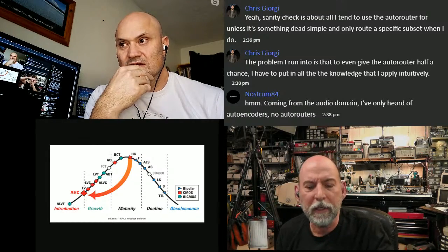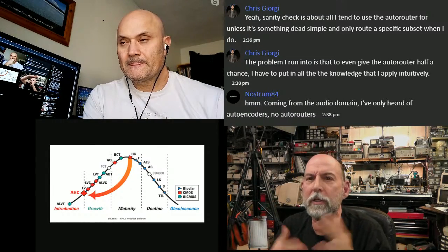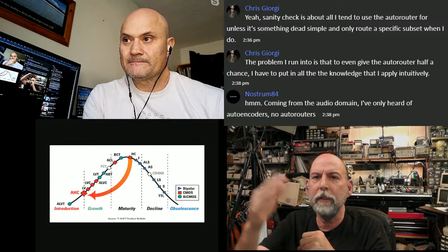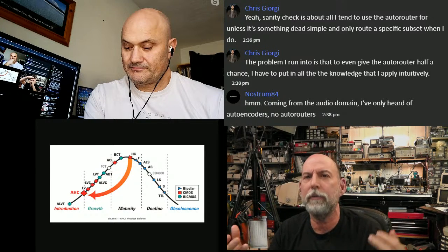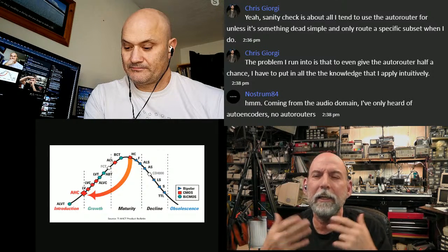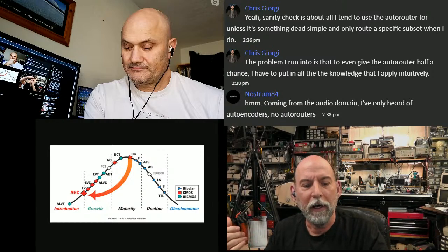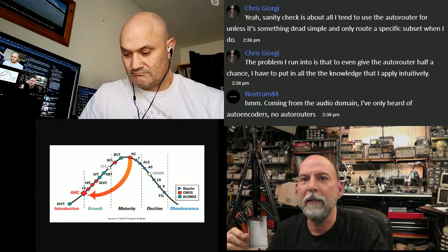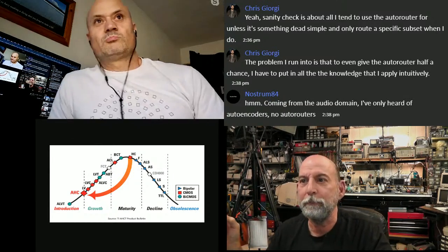That's fine, it's within limits, but if you're doing the statistics of production, the further away you can keep your traces from things like through holes, statistically, the less chance you have of a failure. So I wish it had a sort of hug and push.